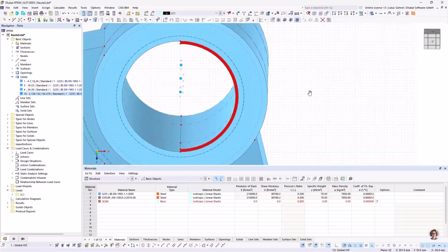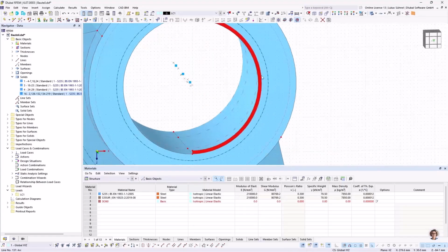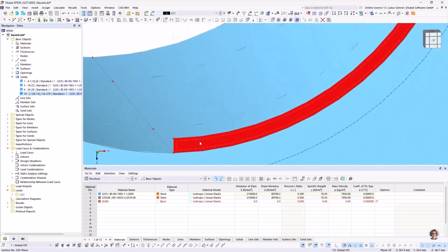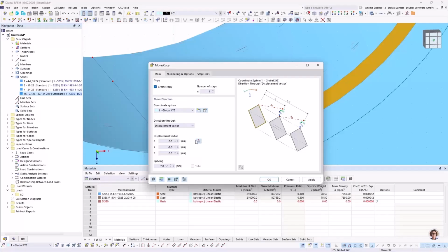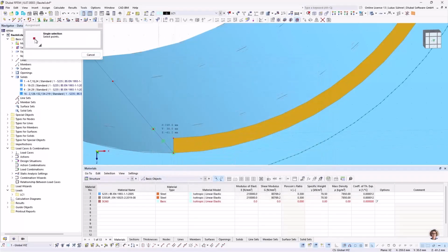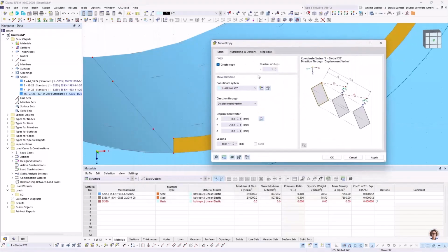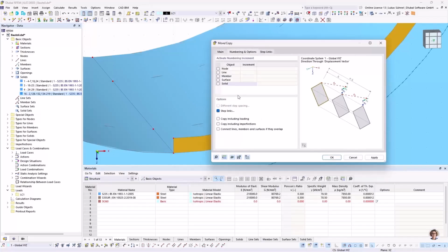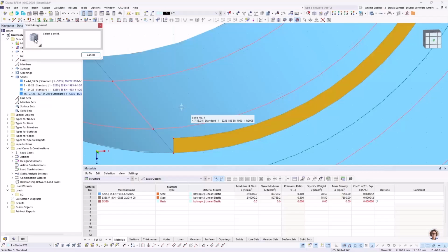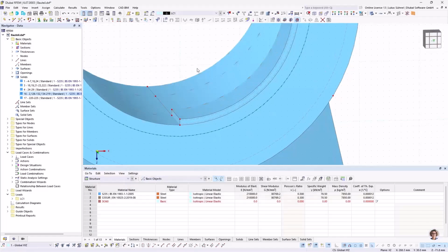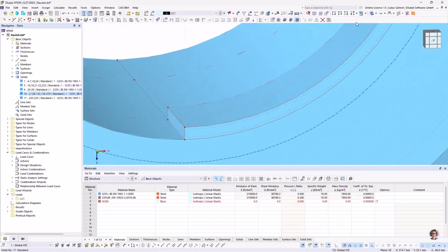Okay, I will cancel the visibility mode, and I will extrude this surface now into a solid a couple of times, for each solid that I have here. So I simply say manipulation, move copy, create a copy. The distance I can pick graphically. I know it's 10 millimeters, but you can also pick it graphically. The vector for copying, and it should also create a solid by doing so. That's the first one, and now I can continue.